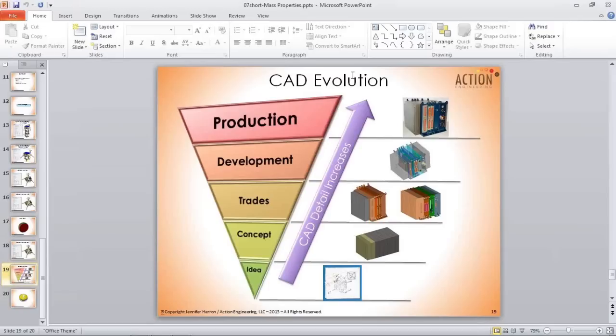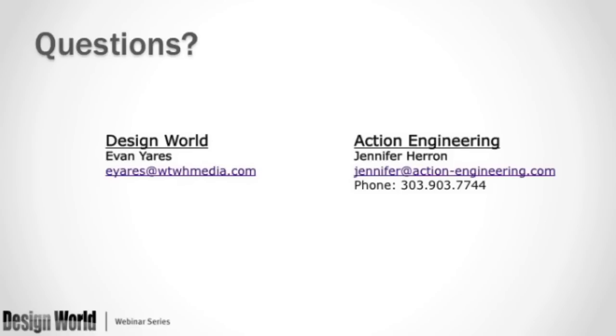Torus shapes, for instance, you can make a torus shape, and it's pretty, and I could apply a mass to it and say, hey, yeah, that's great. Well, torus shapes don't come out accurate for mass properties, for moments of inertia. So at least that has been the case. Now I'm sure all those things are being ferreted out, but that was the case in the past, and it doesn't know that your vehicle shouldn't weigh 20 million pounds. Yeah, well, that should be a good clue to you that something is wrong. Exactly, but the database won't care.